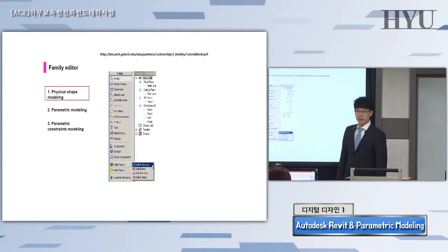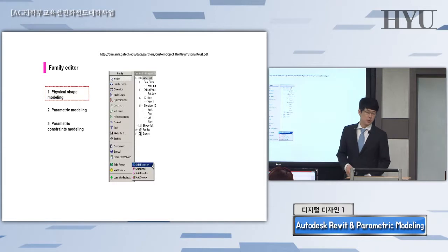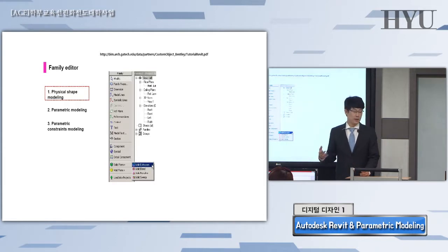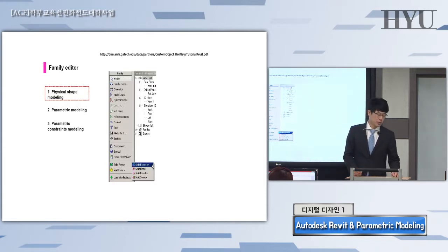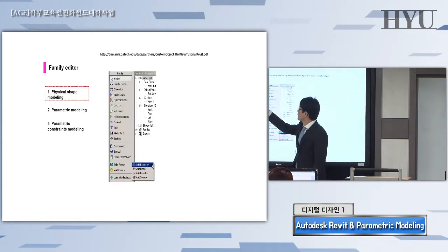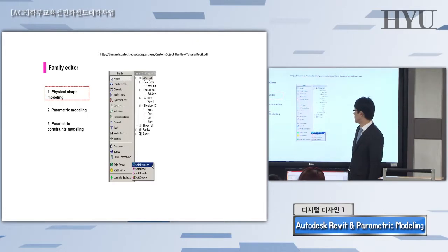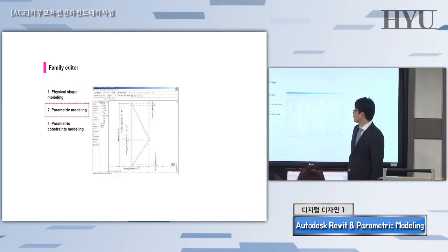By using Revit and Revit's family editor, we try to make some specific type of window panel. Okay, window panels, I told you, are very important for building facades as well as interior finishes. So firstly, we need to edit shapes by using the family editor and parametric model. Take a look at this plan. This is a section profile.